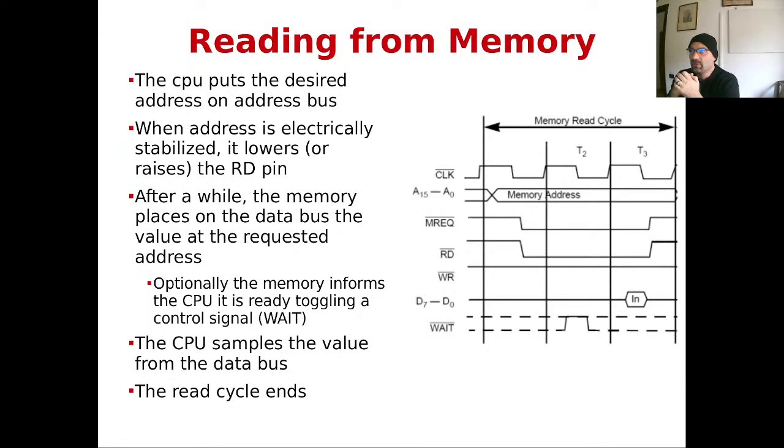As I mentioned before, it's interesting to see what happens at signal level when the CPU wants to read from memory. Remember that inside the CPU everything is orchestrated by a clock, which is basically a square wave where each transition determines one epoch in the CPU time.